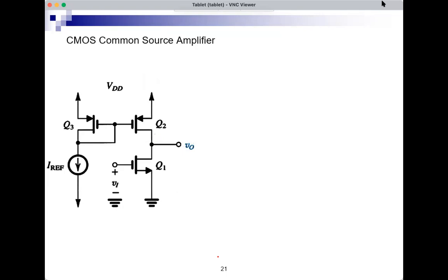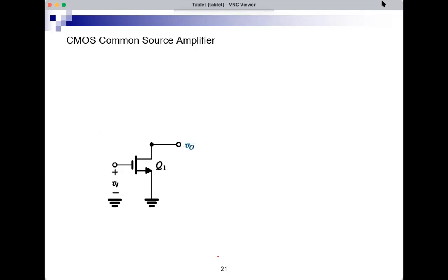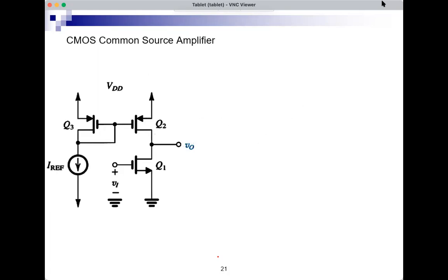Whenever we need a current source, I use IRF with Q3 and mirror it, and I get the current that I need. So if I need the current I here, I'll just mirror IRF using Q2, and I will get my current source. Okay, so this means that I need the MOSFET instead of a resistor. I need Q2 instead of R. Before we continue further, let's see.